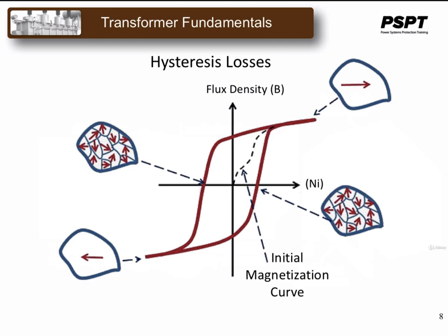Also, transformers are designed to operate at a particular supply frequency. Lowering the frequency of the supply will result in increased hysteresis or higher temperature in the iron core. So, reducing the supply frequency, say from 60 Hz to 50 Hz, will raise the amount of hysteresis present, decreasing the VA capacity of the transformer.